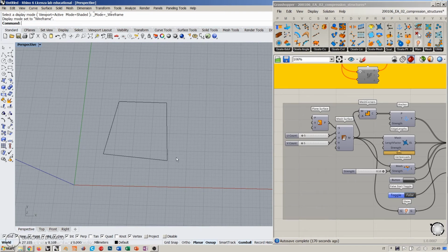Okay, so just follow this, and I want to create other quads which are joined to this one. Okay, so I will create other 3D faces, and just keep in mind that if you want to snap to this vertex here, this is a vertex, it is not an endpoint. Okay, so if you don't activate the vertex snap, you cannot snap to this endpoint here.